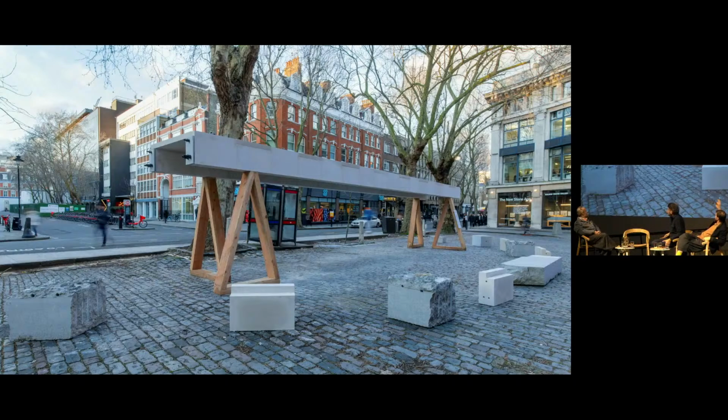It's a 12-meter span, a 450 millimeter deep by 200 millimeter beam, with a 75 millimeter top slab in stone. They work collaboratively together. So when the beam sags, it compresses the top slab. You can see these slightly castellated top profiles, so that they push compression into the top level. Just to demonstrate how simple it is to make a stone beam to replace a steel beam. This has about 10% of the carbon footprint of the steel beam equivalent.